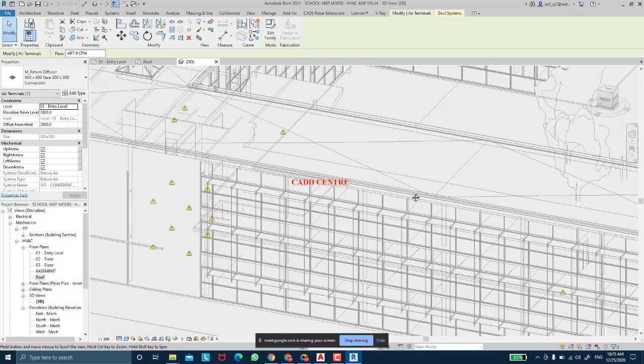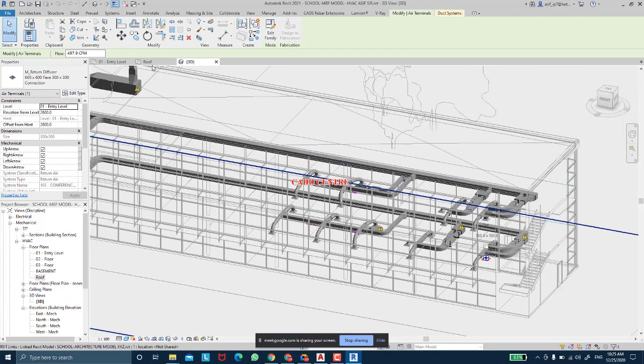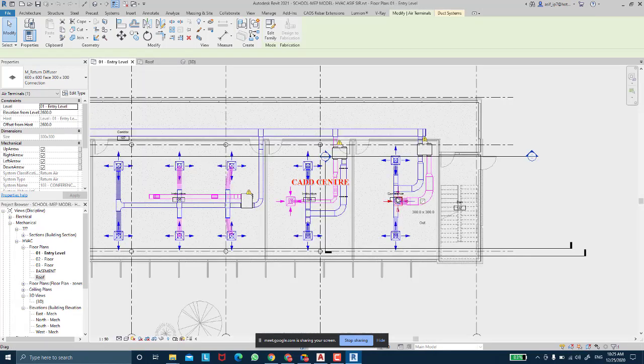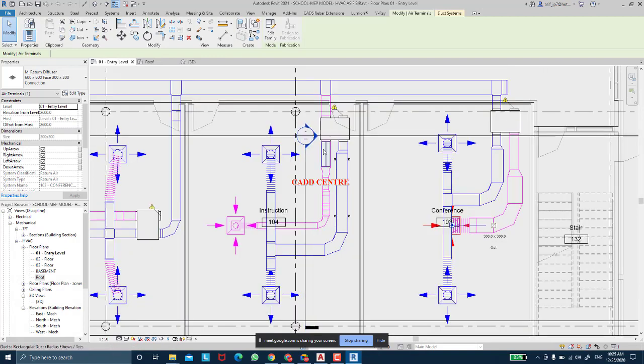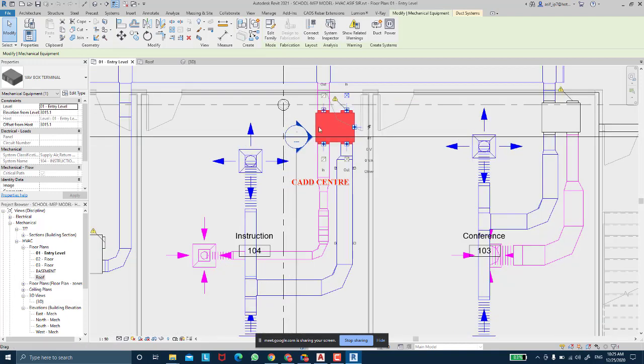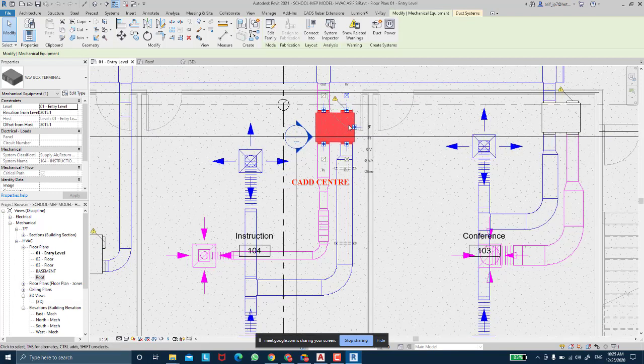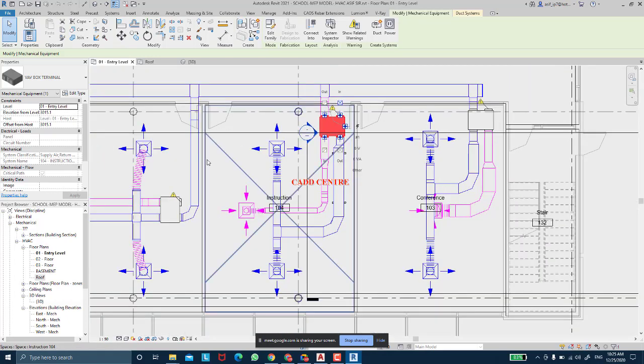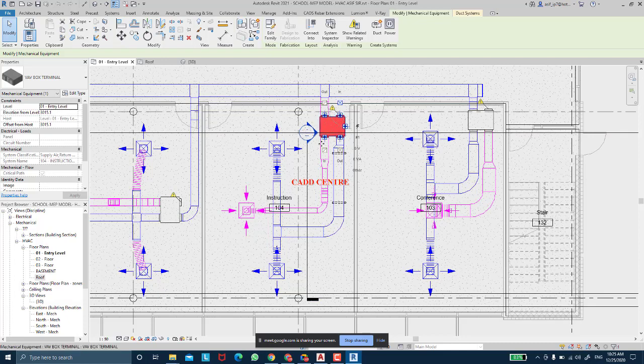Now to control the air conditioning, we also require one more piece of equipment called VAV. VAV stands for variable air volume. This is called a VAV box. It is like an air conditioning controller. Supposing I'm not occupying this particular room, I'll tell the VAV box to shut off the fresh air, so the fresh air will not flow into this room and will stop coming from these diffusers. So this box is like a controller.